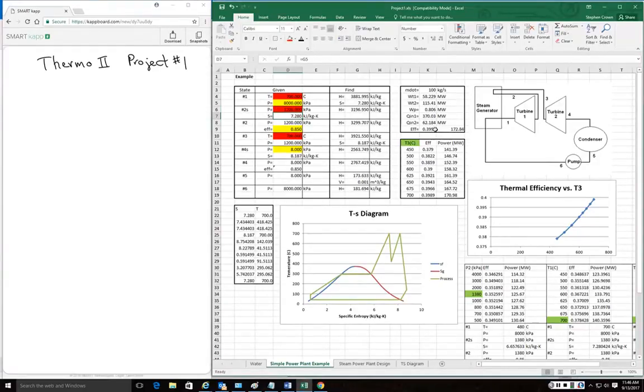And 39.99. So we actually went up slightly, not much, but from 39.89 to 39.99. So there seems to be a little variation in that the new optimal mid pressure has changed a little bit. And if we go in one direction a little higher, see if that goes up or down. It's still going down, so we might consider, say, 1150.